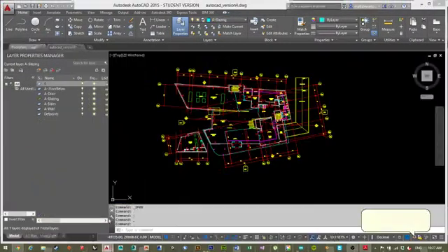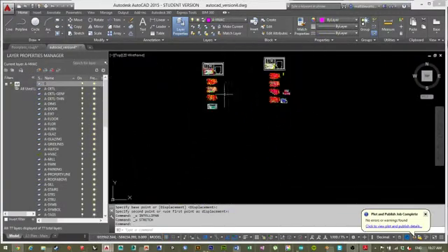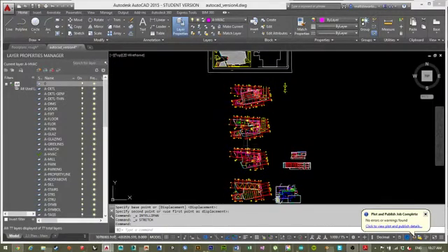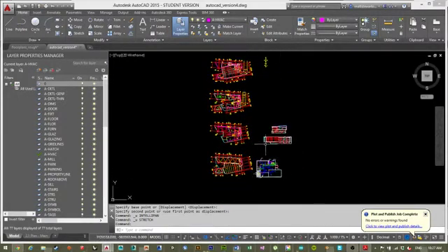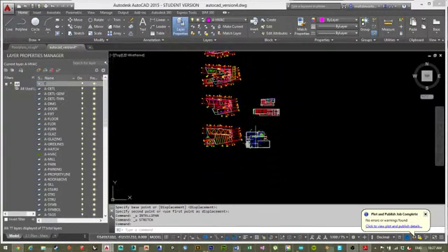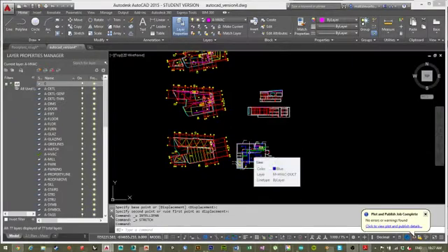On this one here, which is a little more final so it's relatively clean, I have all 3 levels, the roof, my sections and my site plan. Everything's in the same file because it's easy to line them up either vertically or horizontally, and you can build your sections in that file from just drawing construction lines down from your plans, or also just doing a second floor plan right below your first floor plan, so you can line everything up.